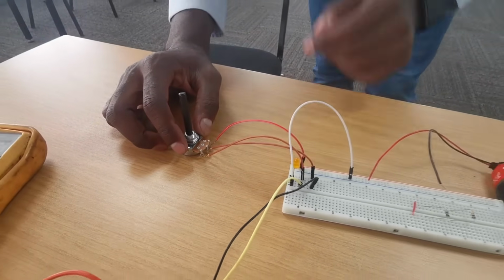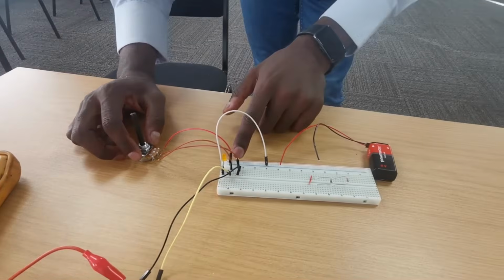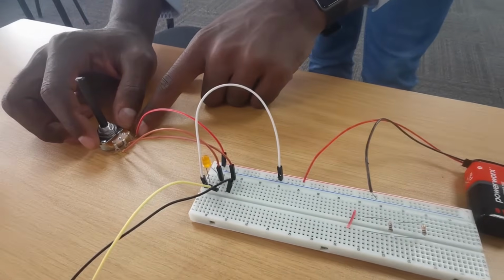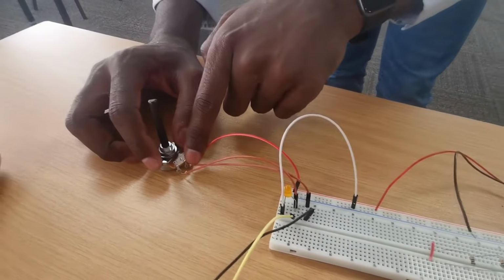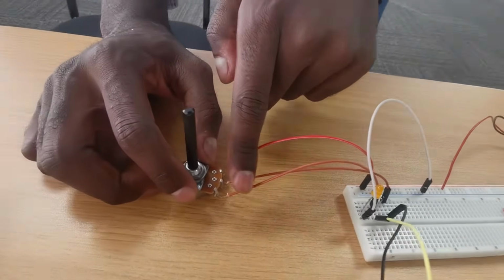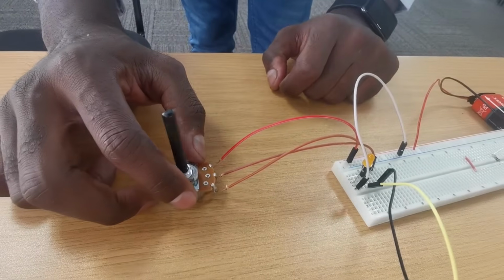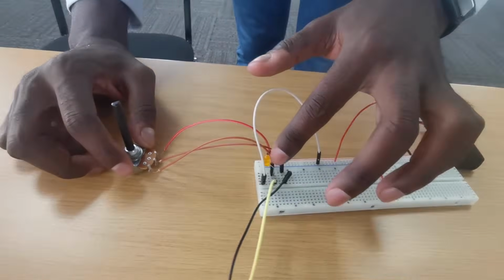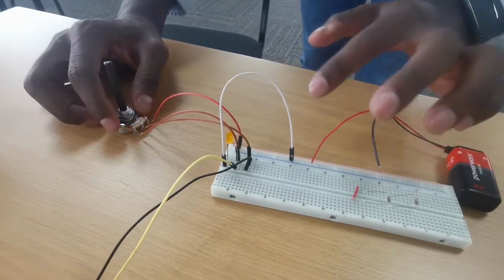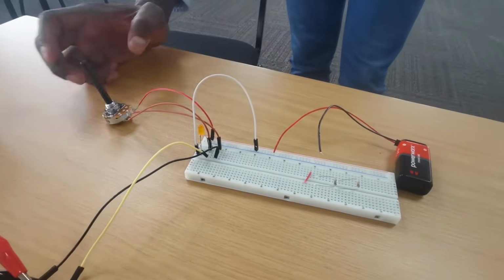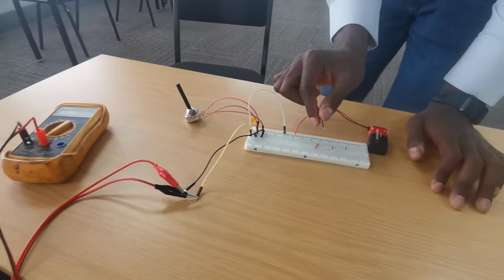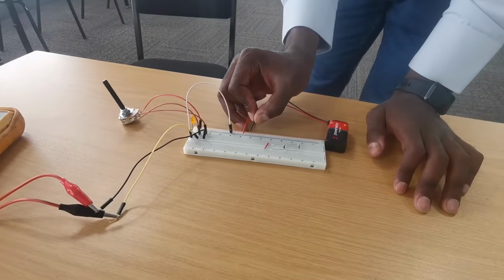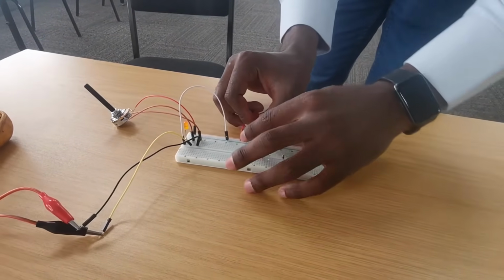Okay, so that's how I've just connected this circuit here. So I've got from VCC goes to the positive leg, it gives it a 9 volt reference, and then your second leg is the positive or the top leg of your resistor, and the third leg is the bottom leg of the resistor. And then what I've done is I've just connected the diode, and then I've connected that to the negative terminal. So when I switch this on, the diode should switch on to indicate that the circuit is complete and current is flowing, and that's what you see there.